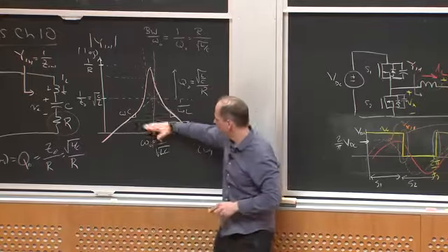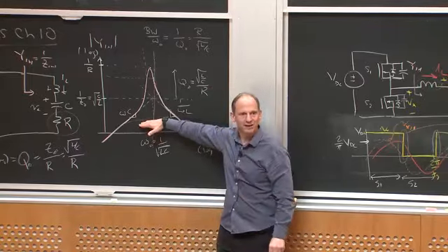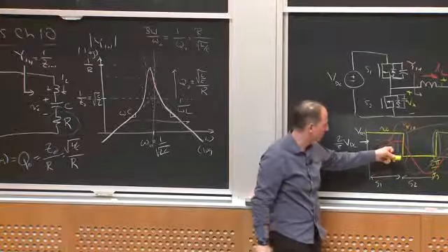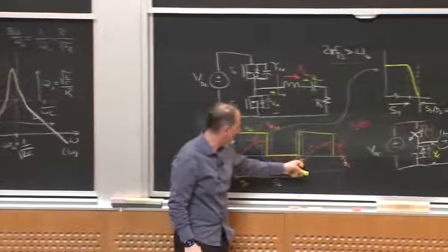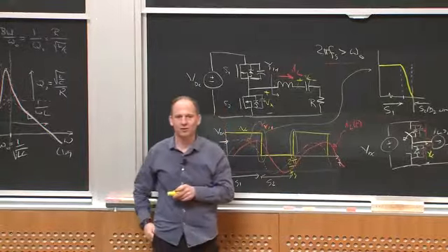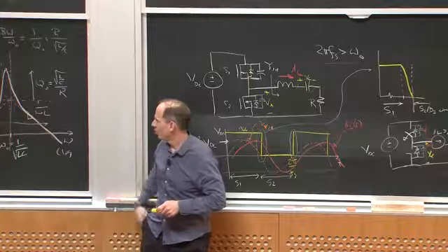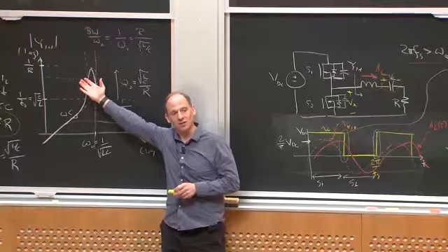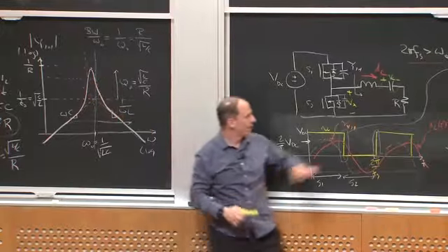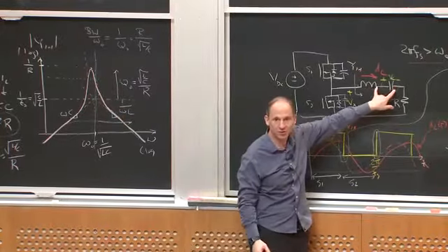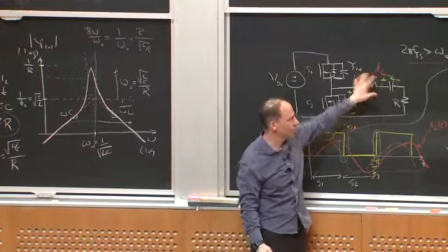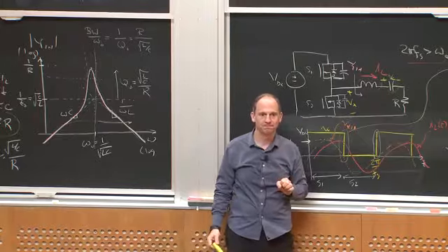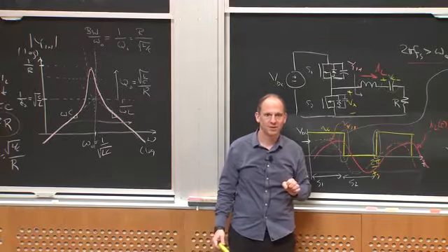And then maybe I don't do a good job of attenuating my harmonics and my current waveforms get distorted, and then perhaps I don't get the right phase shifts for zero voltage switching and all that. So you want Q to be high enough that you get good attenuation of harmonics and low enough that you don't have big stresses on these components and big parasitic losses in those components. Questions about that?